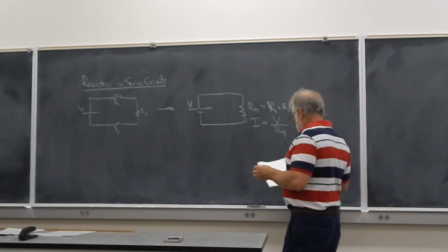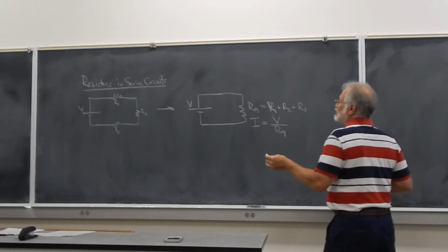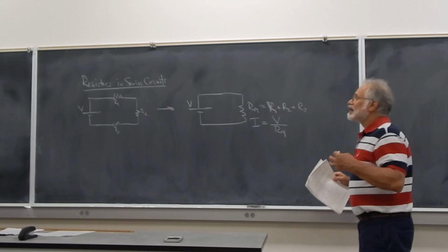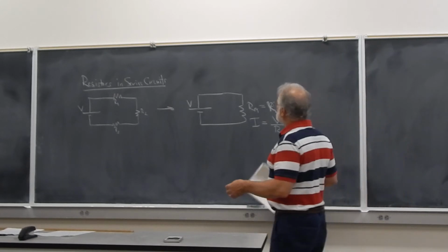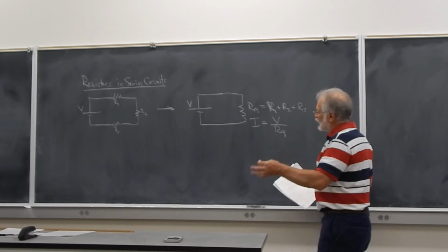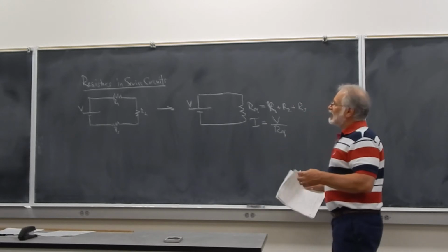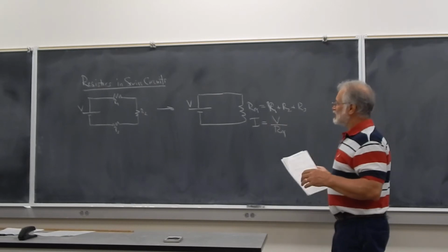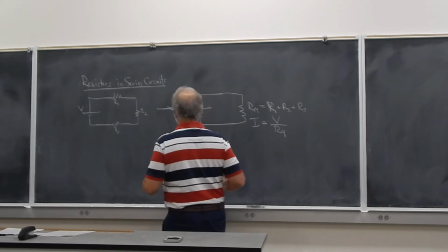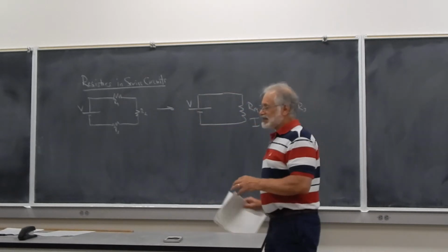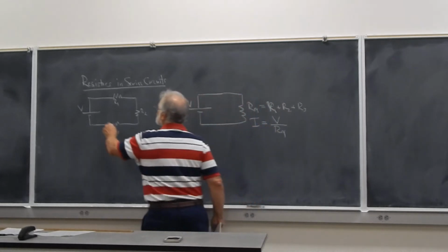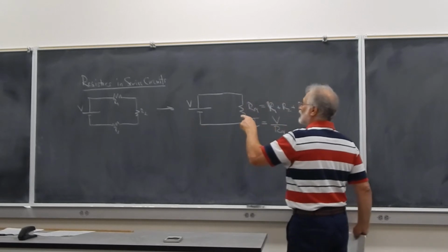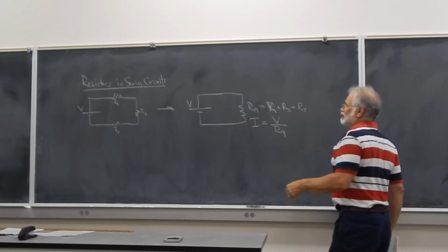And so let's just put some numbers in and see what we can get. Similar to the case of circuits with capacitors, let's find an equivalent circuit where we have one battery and one resistor, and let's find the voltage drops across each resistor and the current that goes through each resistor. In a series circuit, it's really quite simple. Since the current has no choice, the current in this circuit is going to be the same everywhere, and of course will be equal to the voltage coming out of the battery divided by the equivalent resistance.